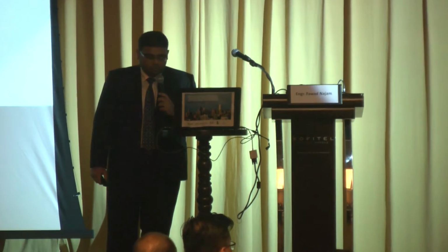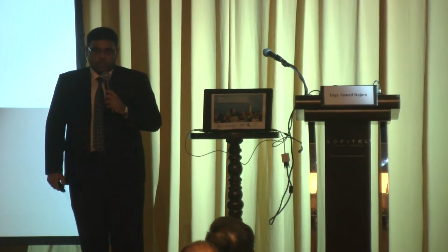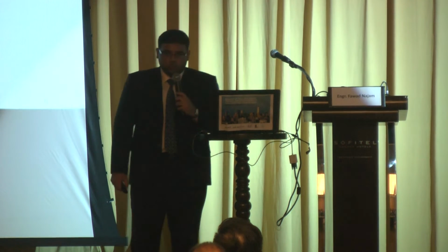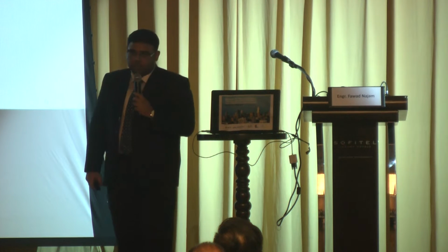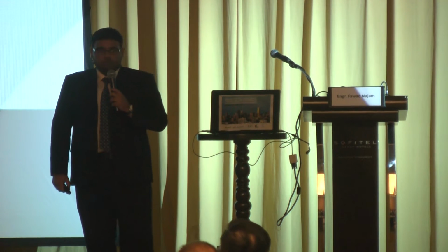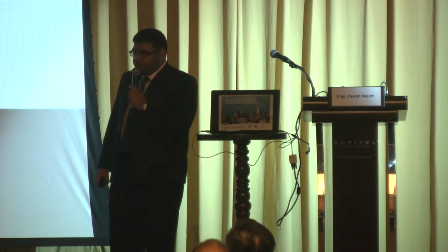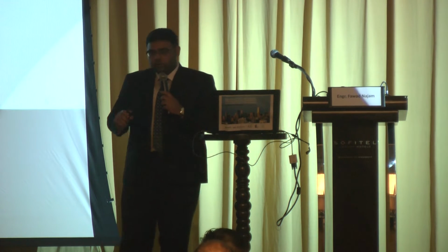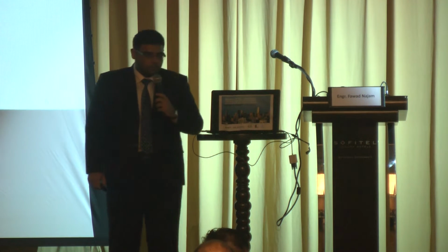So we feel that the idea of modal superposition will still remain in structural dynamics for some more time, not because it offers more convenience nowadays compared to time history analysis, because time history analysis is no more an issue nowadays, but because it provides the response mode by mode. It tells you the constituent of response.